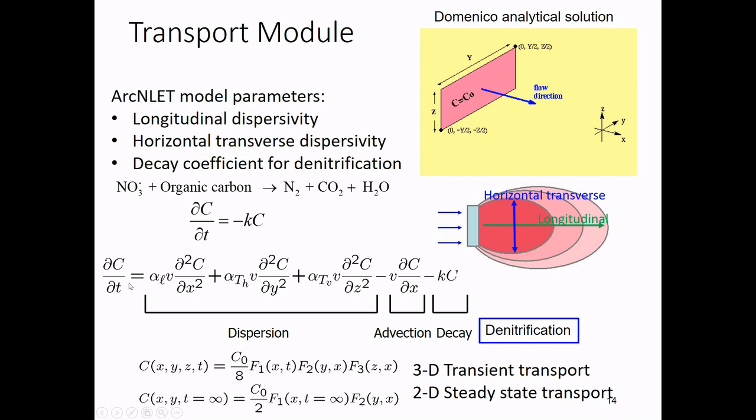We normally solve, let's say for a 3D problem, this so-called advection dispersion equation. So this term is advection, v is the velocity you calculated a moment ago in the groundwater flow module. So the concentration, I say here there's a source plane. This vertical plane, the source plane, and water moving from, say, left to right, right? And all the contaminants, this is a source plane, right?